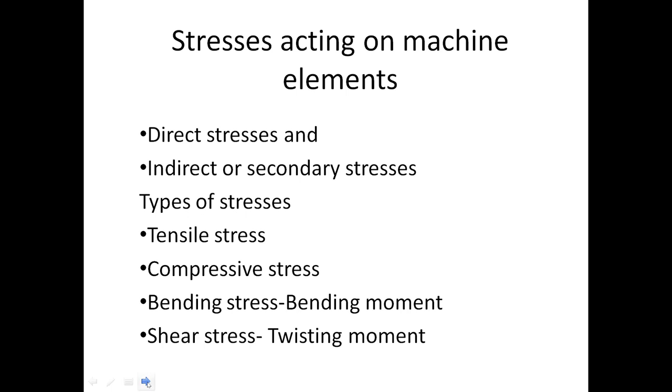And the bending stress is induced because of the bending moment acting on a machine element. The bending stress is induced whenever a member is subject to an eccentric load or an eccentricity is induced because of axial misalignment. In most of the cases, the bending stress is induced because of the external load acting on them. Whenever a shaft is loaded, if the length of the shaft is too large, then bending stress is induced. Therefore, it is essential to estimate the magnitude of the bending stress.